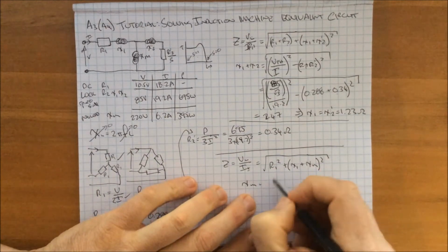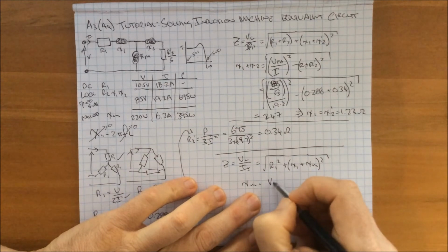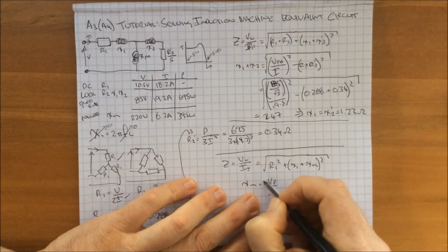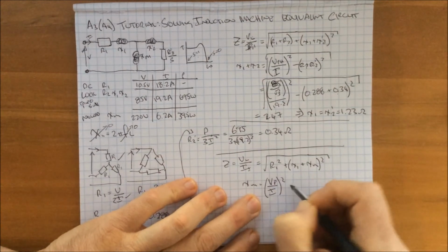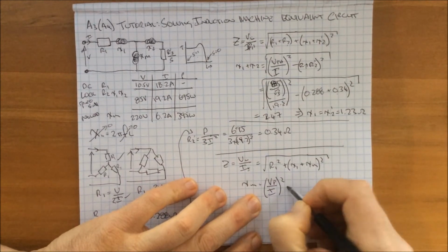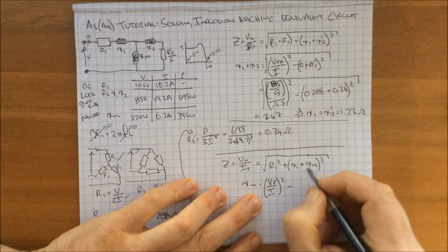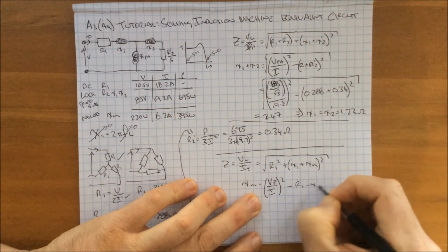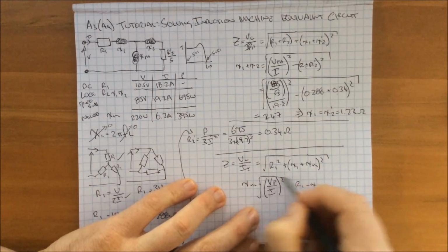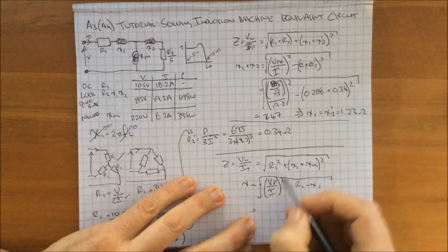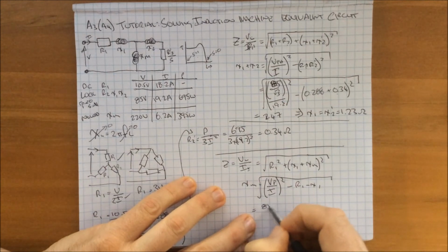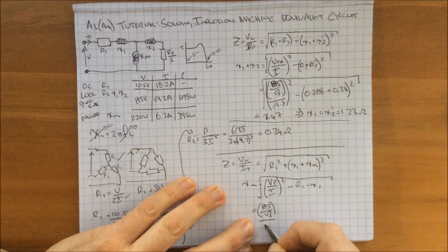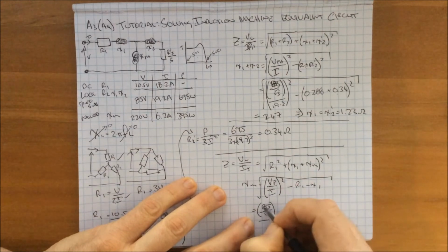And what we can therefore do is rearrange this for XM. And that will be our voltage over our current. Again, that's our phase voltage. All of that is squared, minus R1, minus X1. And if we pump the numbers in there, again we end up with 85 over root 3, divided by, sorry, not 85, 220, my mistake.